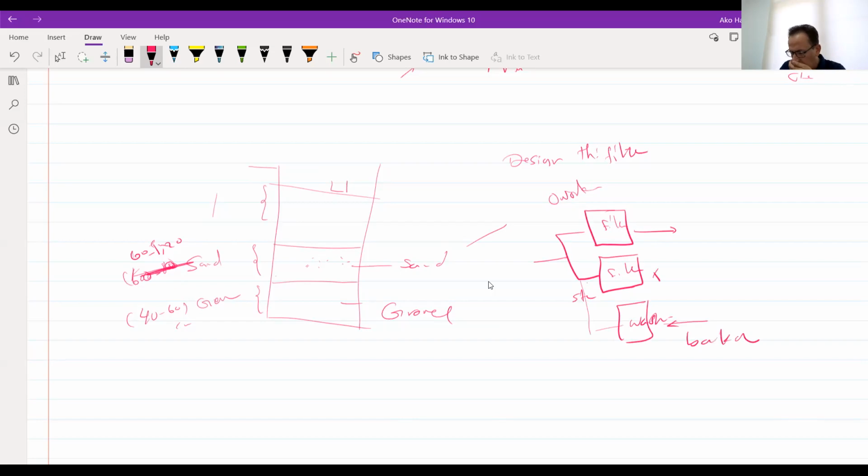Now we have three filter units, and I can have the flow from only one filter. Why? Because one is standby for that one, and one is used for backwashing. Usually, the number of filters should be an even number, and all together those are called a filter bank. Okay, that's one.